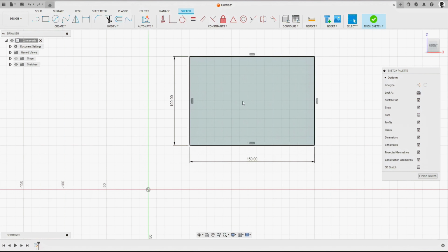And this fillet here is controlled by this dimension here. I move this dimension. I put it there for now. If I then change that dimension to, let's say 25, we'll see that both of these fillets have increased to a 25 mil radius. I'm going to put that back. Let's do 5 mil. There we go. We've got 5 mil there, 5 mil there, 25 and 18.